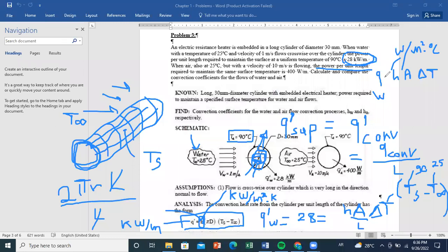So here, let us say degrees if we keep temperatures in degrees. And if you want Q in kilowatt, then H will be in kilowatt per meter square degrees. So here all we did is we simplified by L both terms. So of course, H will remain in the unit kilowatt per meter square Kelvin. Now, if you do exactly the same work for air, you can get the convective coefficient involved in air.